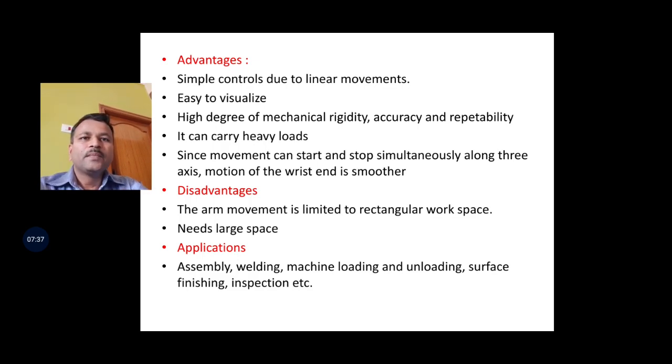For example, a robot has to pick up an object and place it at a 1 meter distance. The first object it took, the second object it will do the same. So even if there are 10,000 objects, the last object also it will place at exactly 1 meter distance. Even small incremental changes will not be there. That is repeatability. The same kind of work it will do for the first job and for the last job, and it will give the same readings. No changes in the readings, no errors.